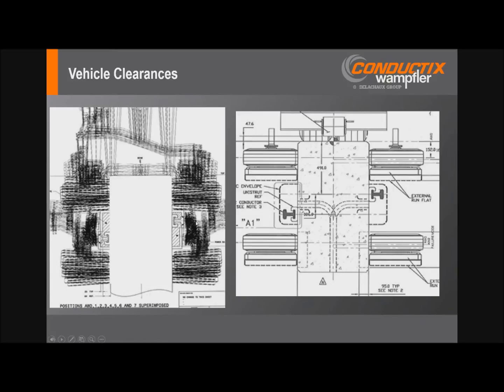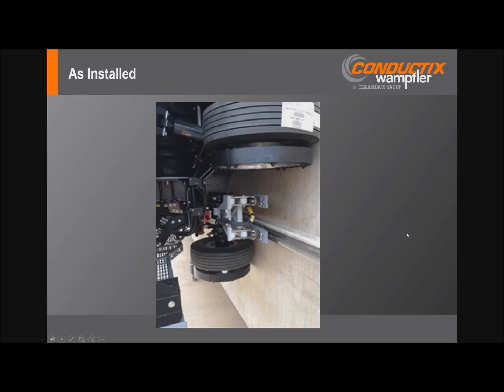So, imagine a flat tire on one side with high crosswinds and sumo wrestlers sitting on one side of the vehicle. You're going to have a very extreme loading condition, maybe a decreased contact between the collector and the power rail. So these need to be understood and considered and anticipated in the design. So here you see as installed. This was the Bombardier Inovia 300 monorail with the phase reversal, the double collector arrangement.